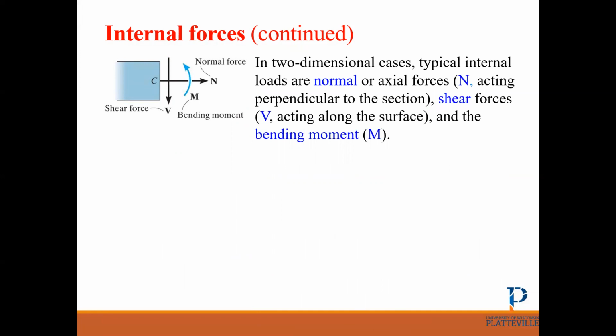Basically we assume all the time the normal force is going toward outside, the shear force going down, and the moment is counterclockwise.